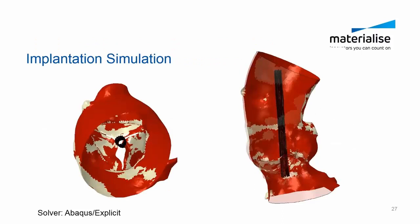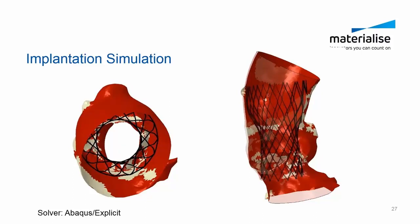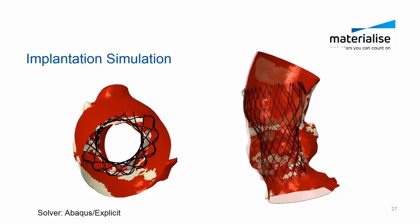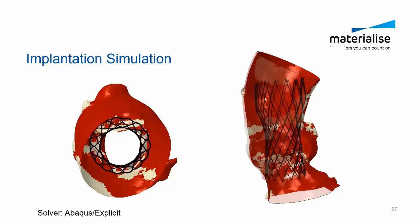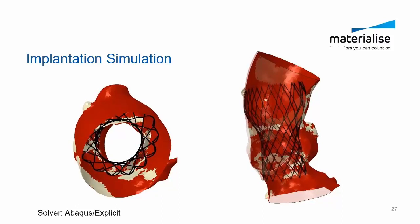What we used is the Abaqus Explicit solver, and we kept the top and bottom nodes of the aorta in place as a boundary condition, and we then released the stent gradually in 3 steps. So we moved the top nodes down, in this case in the first step, and then released them to find an equilibrium position.